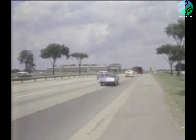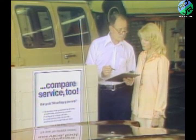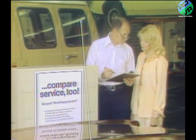Always road test the vehicle with the customer. This is the best way to isolate the customer's complaint. During your road test, try to find a smooth road surface where maximum speeds are allowed. Concentrate on the specific owner complaint during the road test, getting all the objectionable symptoms from the owner's point of view. Remember that some types of NVH may only occur on certain road surfaces that are driven on by the customer. After the road test with the owner, find out as much as you can about the problem.